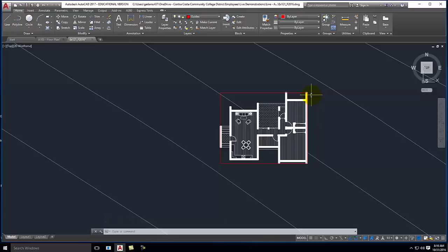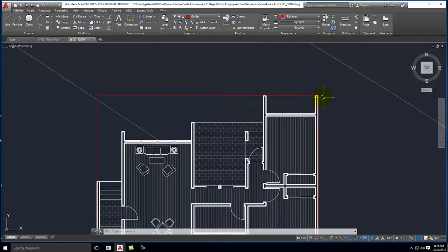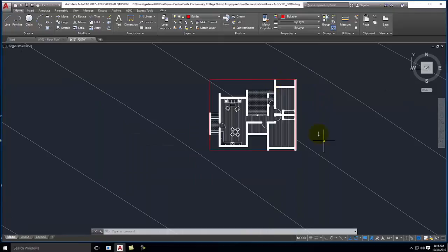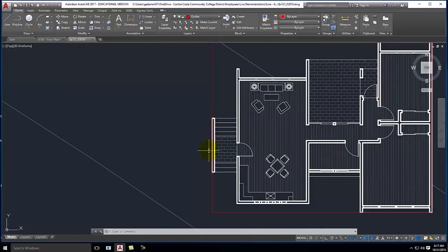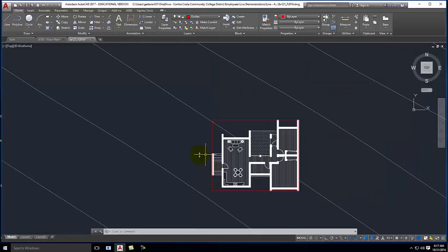It's useful to have this as a starting place because you understand the bounds of your floor plan. And your floor plan is going to look a little bit different. You just want to make sure that this box completely encloses your entire floor plan and that the furthest most point on all four sides is covered. So here I have to reference this little staircase because that's the furthest most point to the west of this particular floor plan. So I have a bounding box that goes all the way around my work.